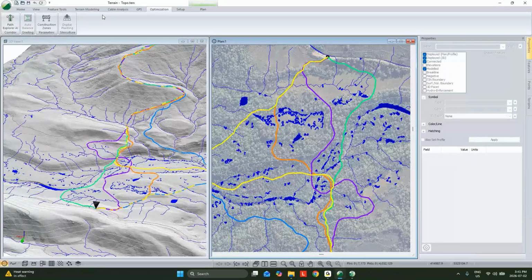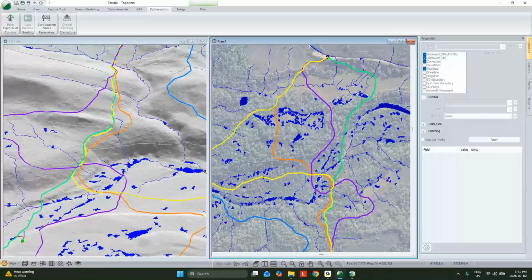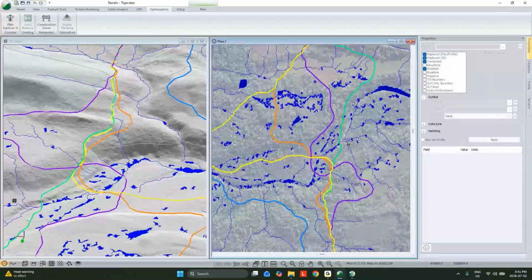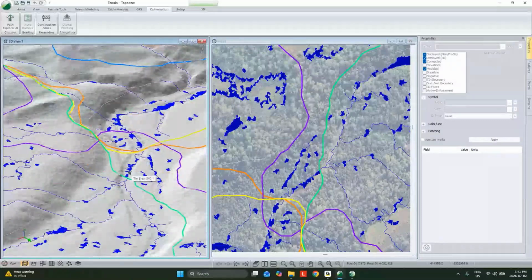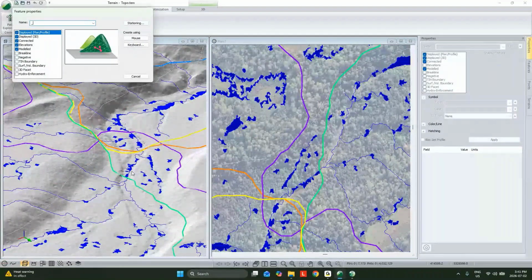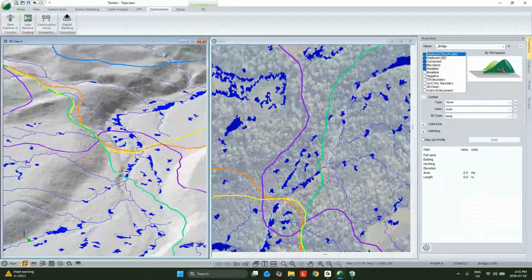I suspect that's not really what the question asker is looking for. It's more, if I have a river or something like that, can I choose where the stream is pinched off? And in that case, you can. There's a few different ways we can tackle that as well. One could be that we manually choose the location of our crossing. So maybe I just come down here and say that I want this to be my bridge site. So I'm going to make a new feature. We're going to go from one abutment to, and actually watch me choose a bad spot for it. We'll go over here.